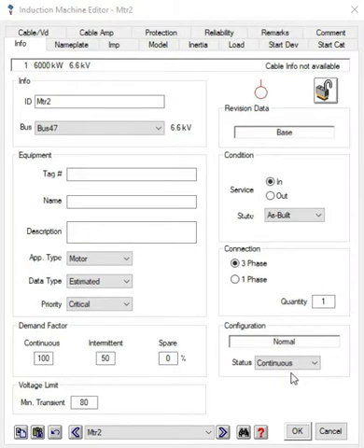If I talk about the industry standards, AC control devices must not operate below 85% of the rated nameplate voltage, and for DC it must be above 80% of their rated voltage. So as a result, studying the dynamic behavior of motor starting is critical, and engineers must know how their system behaves when they are in use.